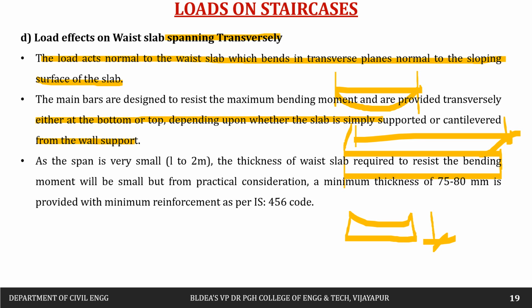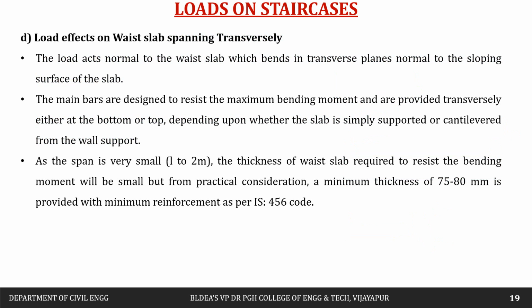Therefore the thickness of the slab will be much lesser, but from practical consideration a minimum thickness of 75 to 80 mm is provided with the minimum reinforcement as per IS 456. These are the minimum requirements which have to be satisfied to design the staircase.